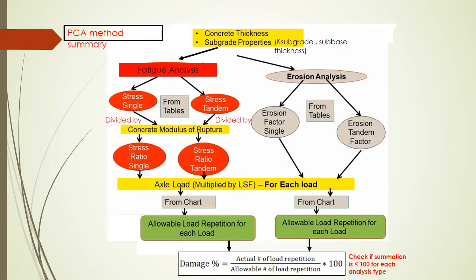This slide here shows a summary of the PCA design method. First, you assume the concrete slab thickness. You will be given the subgrade properties like K subgrade or subbase, and also you will assume or be given the thickness of subbase. Let's talk about the fatigue analysis.